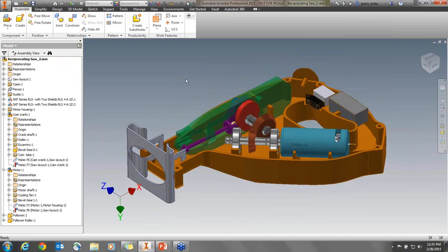We'll use color mobile groups to distinguish component relationships and manually create rolling 2D contact and spring joint types. Then we'll define some joint properties, impose motion on a joint and define gravity. We'll get into the output grapher a little bit, and then run the dynamic simulation to see how joints, loads, and component structures interact as a moving dynamic mechanism.